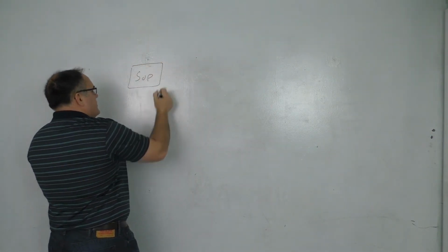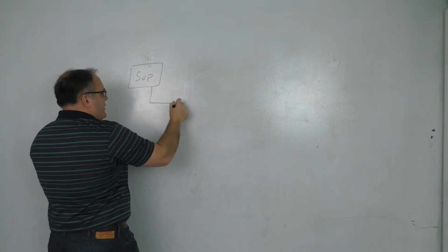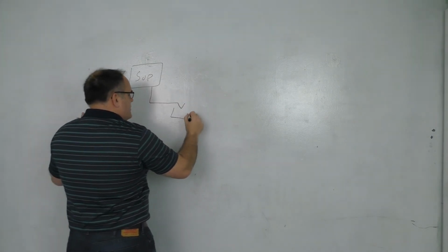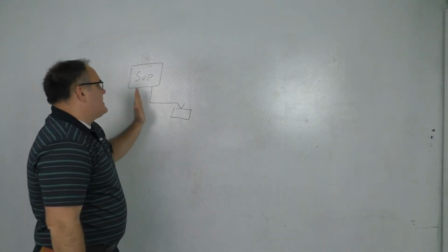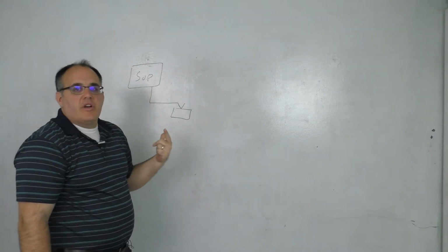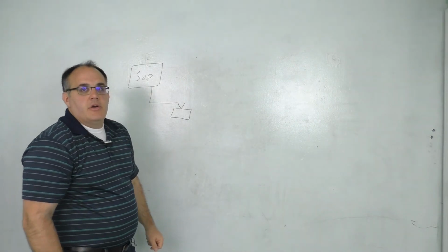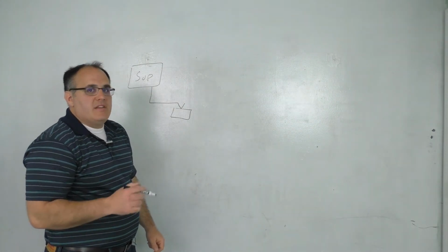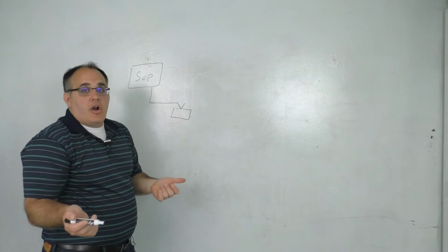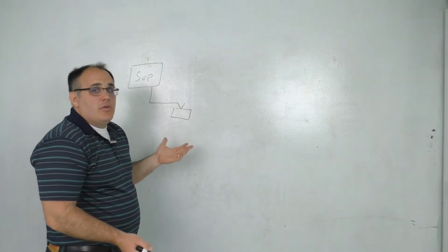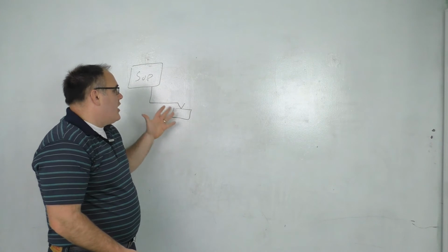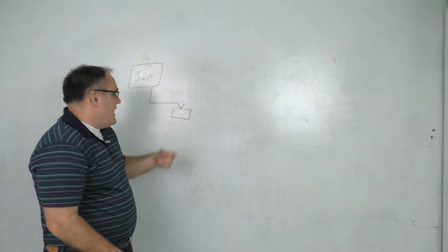First thing we do is we have our supervisory device, and from there we go to our controllers, okay? So first thing we're going to decide is what is our baud rate and our network ID for our BACnet MSTP network. Once we've decided on baud rate and network ID, and we've got our addressing scheme laid out on our job drawings, our installers will go and start to address our controllers.